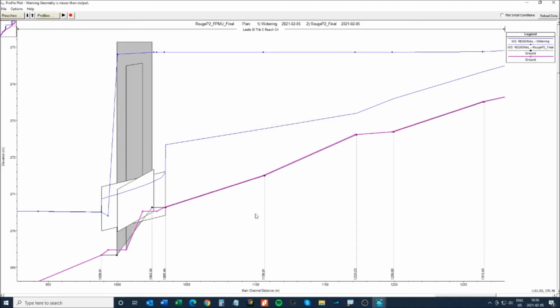and we'll compare the geometry as well. Okay, so we can see this is the original width of the road. Now we have increased it. We have lengthened the culvert as well. There's a little bit of an adjustment in the bottom elevation, and the previous regional flood line was actually spilling over the top of the road, whereas now it's much lower, and obviously it's not spilling.